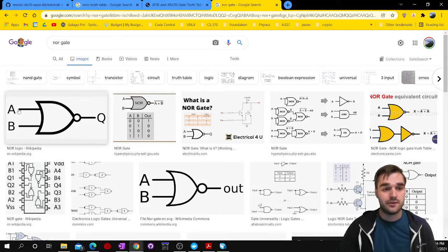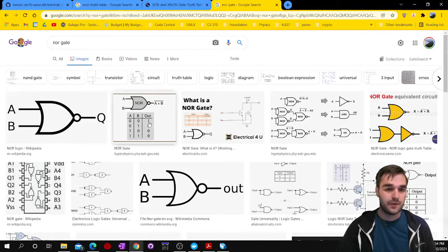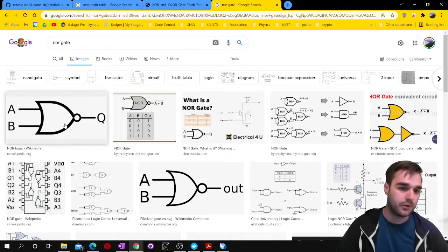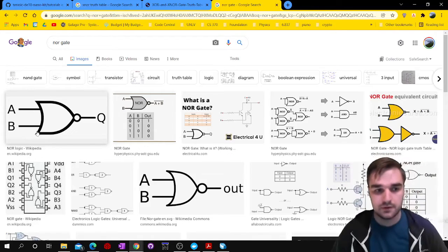Maybe these inputs are connected to a security system in your house, and you want the alarm to not sound if everything is off, but if any one thing is on, you're going to give a 0, and that 0 is going to trip the alarm, however it's set up down the chain. But you can chain logic together like this, and you can create all sorts of cool stuff. This is the basic building block that you're going to build anything out of.